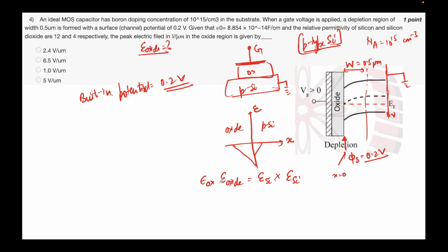Once again, sir, one doubt. Yeah, go ahead. On the oxide side, how is the electric field negative, sir? Okay, because E is the minus of del of V. That's the phenomenon. Let me just see if it's positive or negative. I was just drawing from the PN junction because of the familiarity, but let's analyze that. I was just trying to emphasize this discontinuity here, but let's be correct. Let's try to find out whether the electric field will be positive or negative.